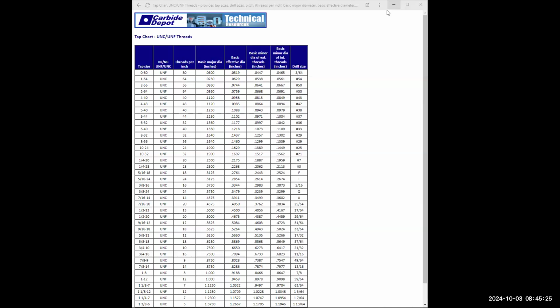All right, so this is what we have right now. And we need to start projecting lines downward. So go to OSNAP, type in OSNAP, enter. Sorry, I had to hit the escape to get out of that mode. Type in OSNAP. And I want to make sure quadrant is turned on. Quadrant. Select OK.